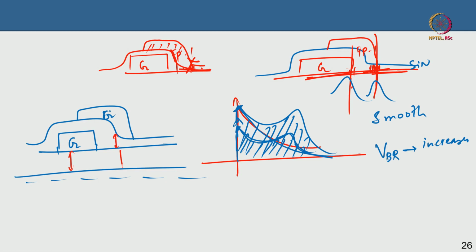So for this gate the distance from the 2DEG to the gate metal is d, but for this gate the minimum distance from the 2DEG to the metal is actually d plus the silicon nitride thickness, t silicon nitride, which could be 100 nanometer.